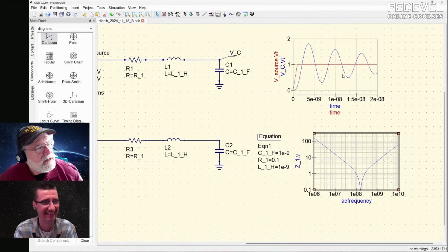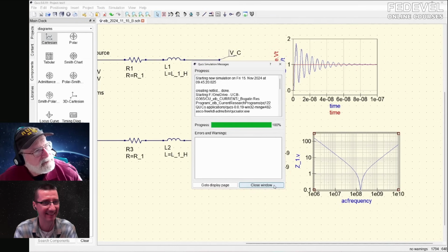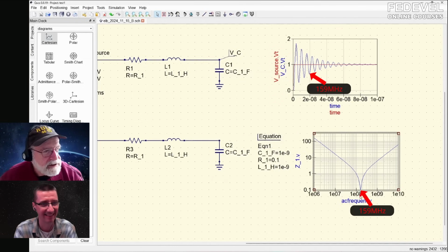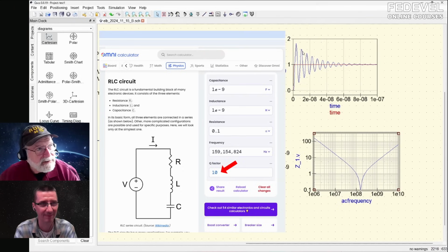And so now we're looking at the transient. Let's do the rerunning, a longer time for the transient simulation here. So here's that transient simulation. Here it is in the frequency domain. And sure enough, hey, it's an RLC, it's a series circuit. And so here is the impedance at the low frequency end, which is related to the ESR, and that was 0.1 ohm, and there it is, 0.1 ohm. We see the behavior over here for an ideal capacitor of 1 nanofarad. Here's the behavior of the ideal inductor from this guy. So it's a series RLC. Now this is underdamped, and we have a really sharp peak. And this is a high Q. And after all, we saw it was 10.